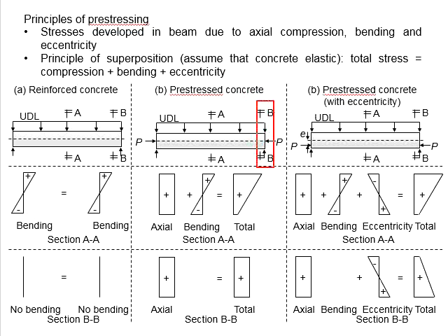Next, we look at the support of the pre-stressed concrete. The pre-stressing compression force will cause axial compressions onto the beam element. However, as the section here is at the support, there is no moment generated by the external UDL load. Therefore, the total stress acting at the support here will be the same as the axial force acting on it.